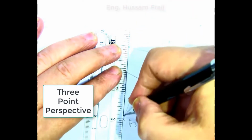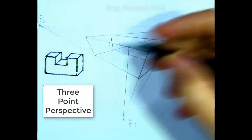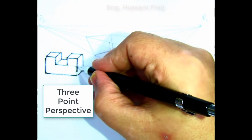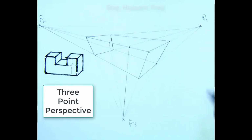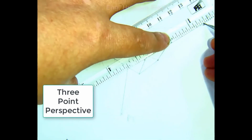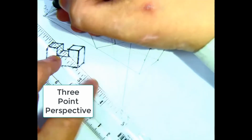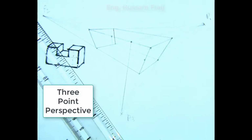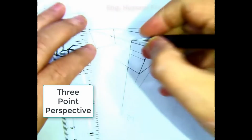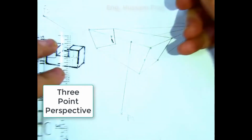From these 2 points, connect down to point 3 like this. Now if you notice, this line is almost half the distance from here to here. So I will choose almost half the distance here, and connect it to the right and to the left. Now as you can see, we generated this slot or groove.